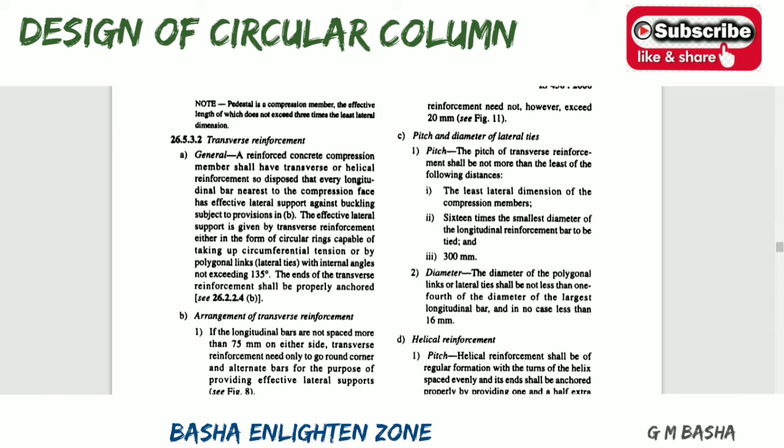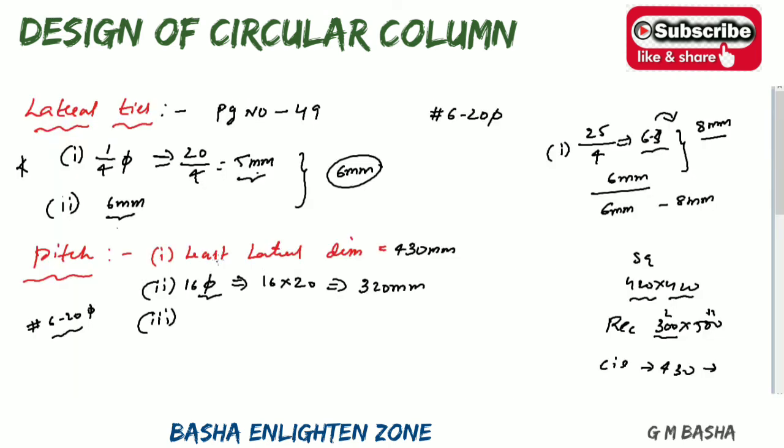Third condition will be 300 mm. Okay, 300 mm. So see here, out of the three we have to follow the least value. So 430 will be higher value, 320 will be higher value, 300 is the least comparing these three. So therefore we are providing pitch of 300 mm.